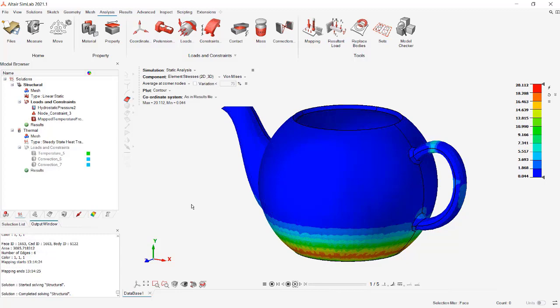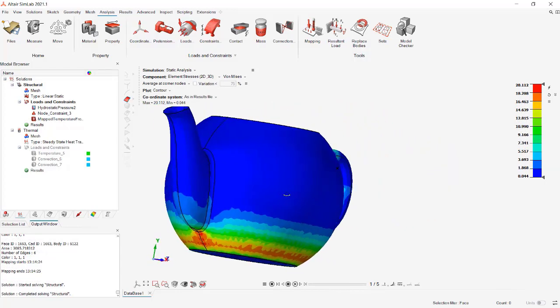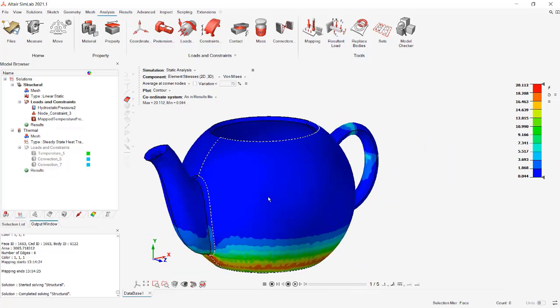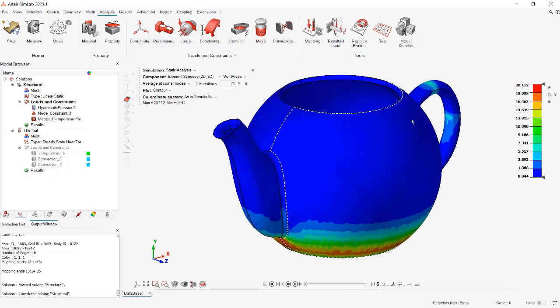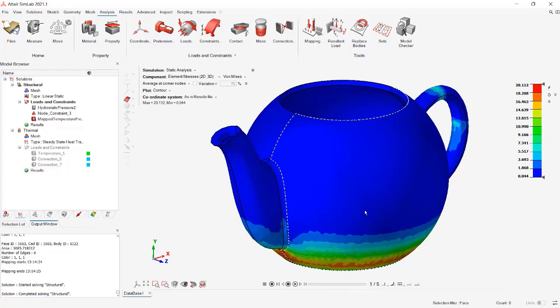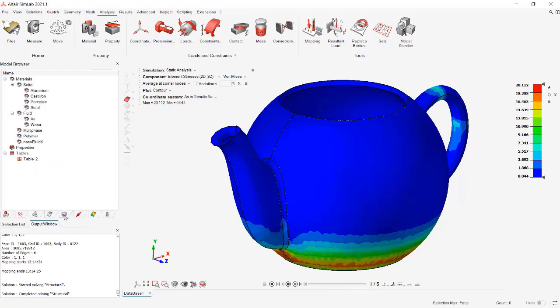All right, now we've seen some changes around the value, and what we can take out of that is that from 0.9 megapascal, by adding a different consideration to our problem, which was adding a heat source on the bottom side, we now see that the stresses are higher than our allowed stress from our material that we've seen.